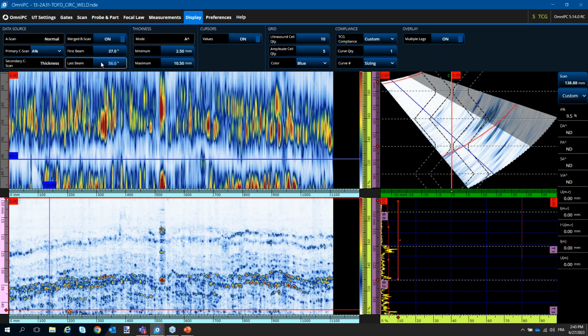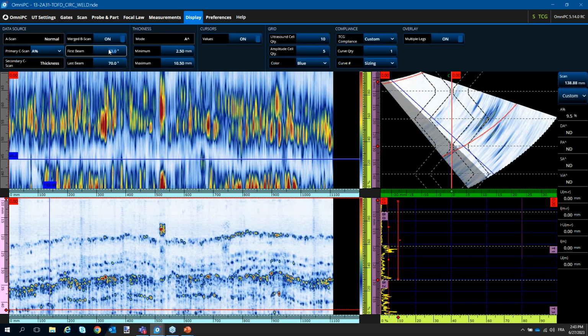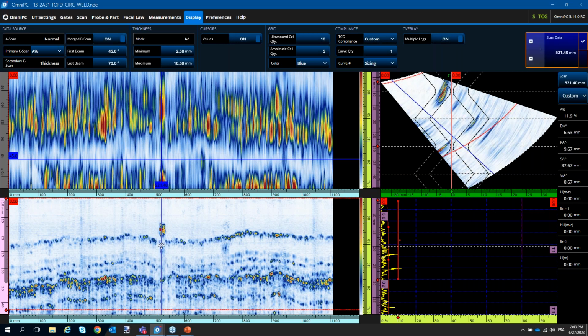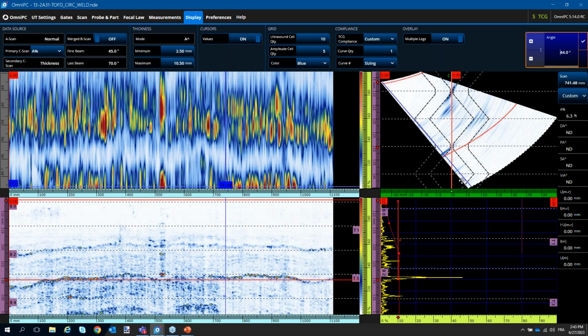And this is a little bit too much. I'm going to leave it as high as I can and rather try to optimize from the lower angle. So I may want to pass the root a little bit. Let's go with 45 and see. Clear, correct light, a bit of porosity, and I want to deactivate it, make sure I did not forget anything.